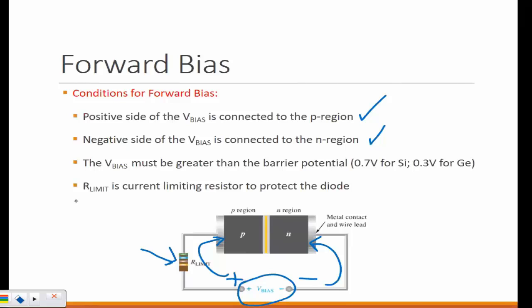You see the subscript is telling you it's a limit. If you have excessive currents, again, in a lot of applications we do in the lab, you're not going to damage the diode. But if you have high voltage, high current applications, it's just a safe measure of having a resistor. So the limiting resistance is just to protect the diode.